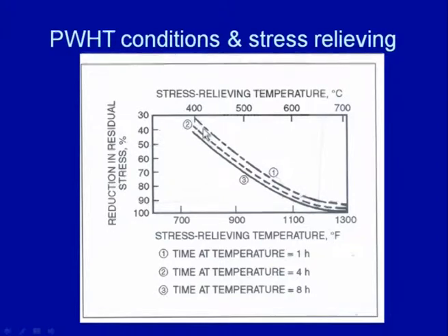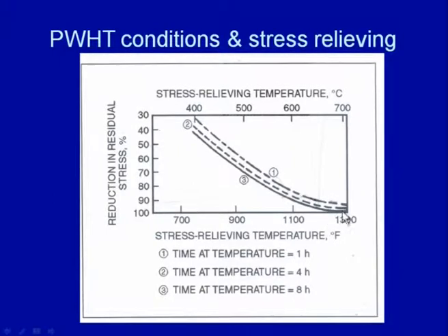The higher the temperature and the longer the duration, the greater the extent to which the residual stresses will be relieved. You can see that more than 90% of the stresses are relieved with exposure at 700 degree centigrade for durations varying from 1 hour to 8 hours. Almost all the residual stresses are relieved with exposure at 700 degree centigrade for 8 hours.